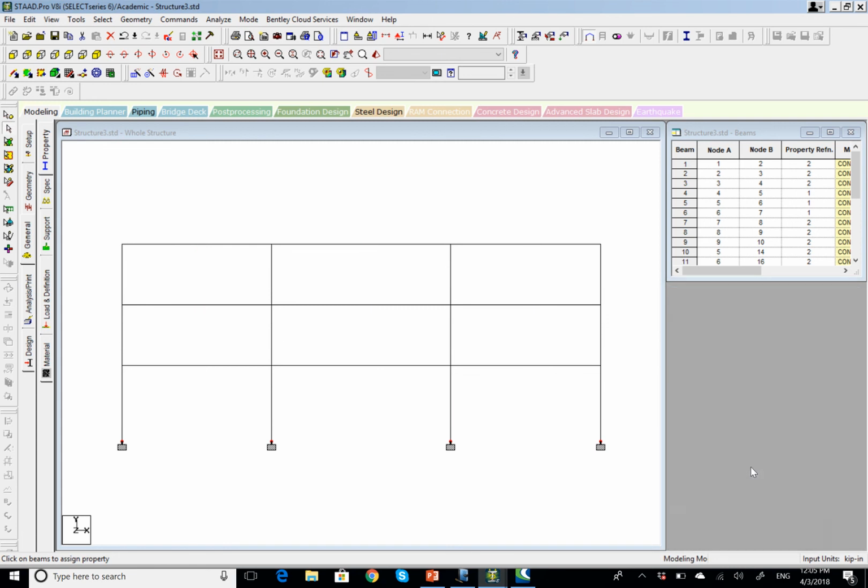And then close. That's a good question. Do we need to have that selected as steel instead of concrete? What do you have in your project? Those are reinforced concrete, okay? So the material is concrete. I typed in 40 by 20 and it's showing 480 by 240. Is that my units? What's going on there? Just make sure that the units is in inch, not in feet.